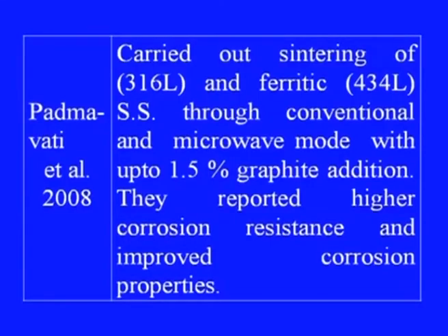Then Padmavati and his research group carried out sintering of 316L stainless steel and ferritic stainless steel, that is 434L, through conventional and microwave modes of heating with 1.5% graphite addition. They found higher corrosion resistance and improved corrosion properties with these microwave sintered products.